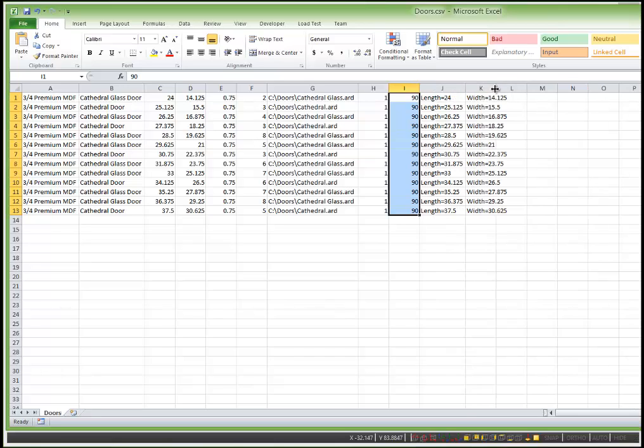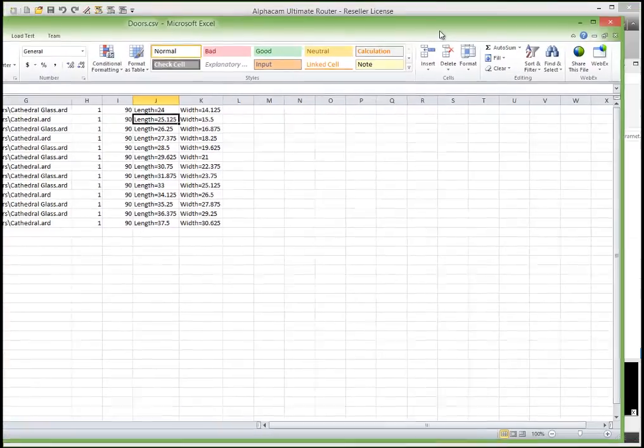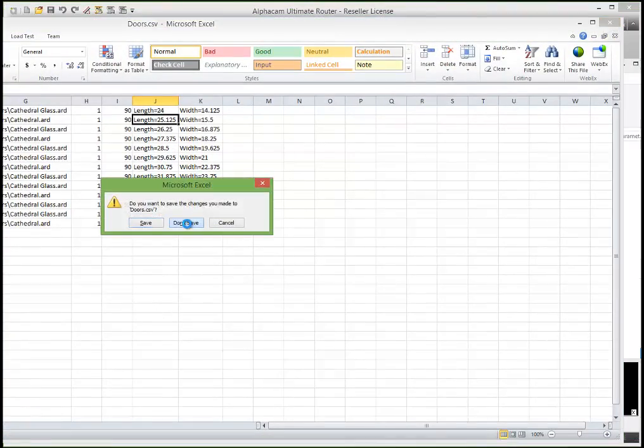And now here's how hCAM handles your parameters. In your comma separated file, you can put the name of the parameter that you're pushing in the file, the equal sign, and then the value for that. And literally there is an unlimited number of parameters that you can pass to your files through this mechanism. hCAM does not restrict you as to how many parameters you can pass.